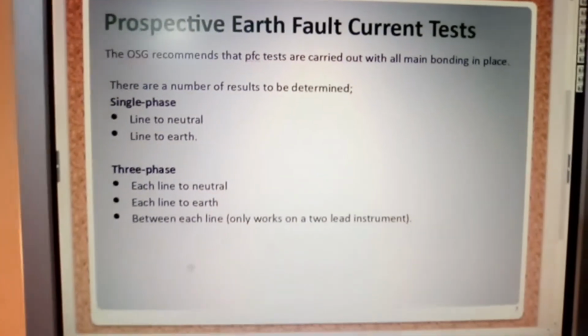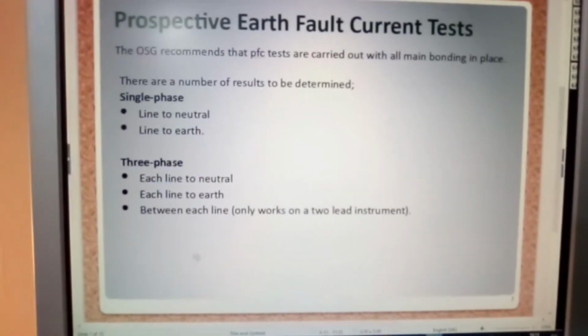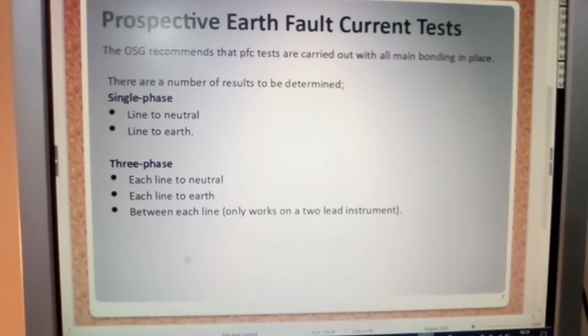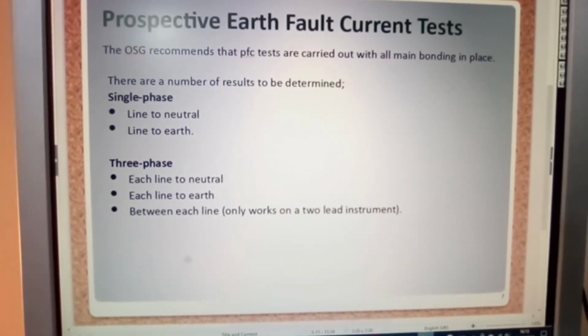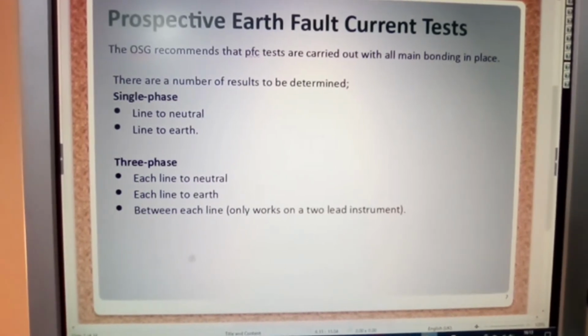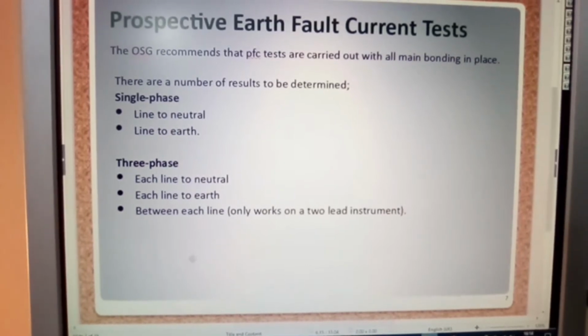That is to make sure that if a fault occurs on some pipe work, it does not cause damage or injury to anybody else, that it will go straight down to earth, or the protective mechanisms will allow the protective device to operate, thereby removing any electrical potential.